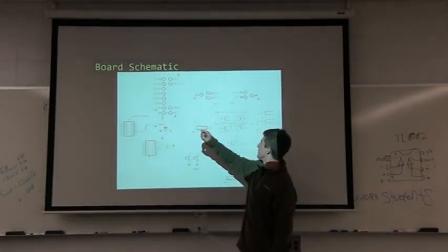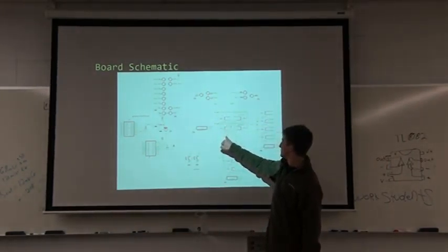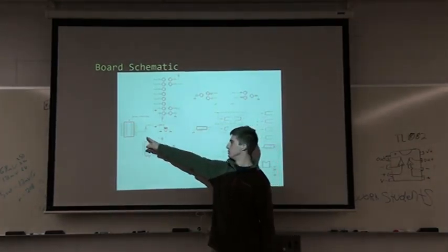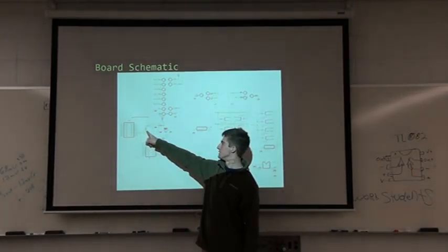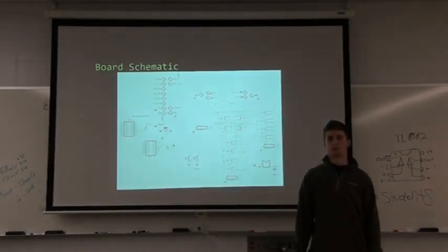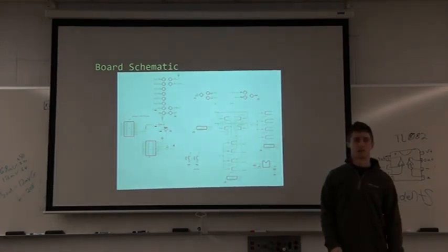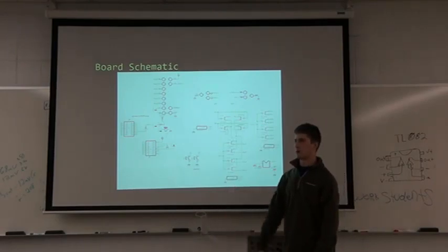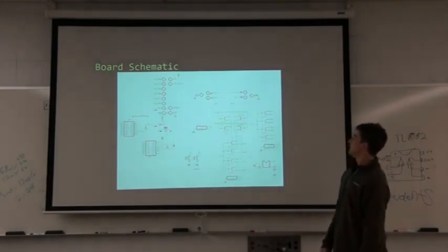This pin over here is going to be connected to this pin over here as well. This resistor is so that the current doesn't get great enough to blow out the diodes that prevent reverse polarity in the comparator input for the analog input.